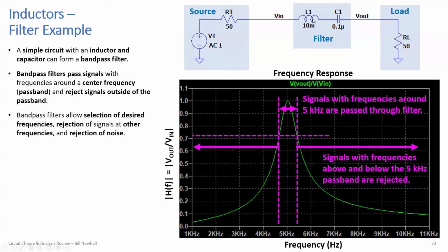If you had plus j10 ohms and minus j10 ohms, they cancel out and you get 0 ohms. At some frequency, this filter looks like a wire with a little bit of loss practically, and it looks like this source is connected directly to this load.